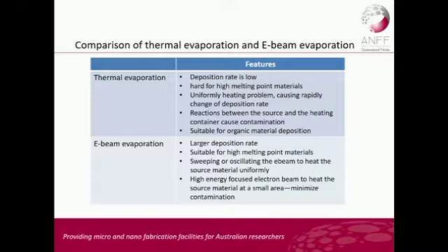For E-beam deposition, we have a large deposition rate and it's suitable for high melting point material. During the deposition, you can sweep the beam to heat the source very uniformly. And for E-beam, we only heat the source, not the crucible, so we can minimize the contamination.